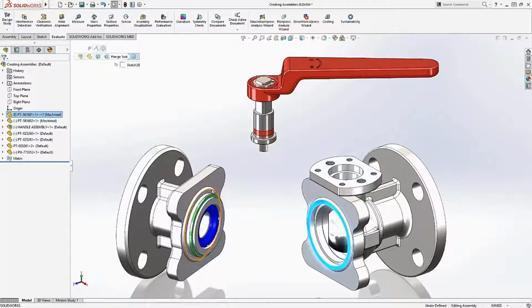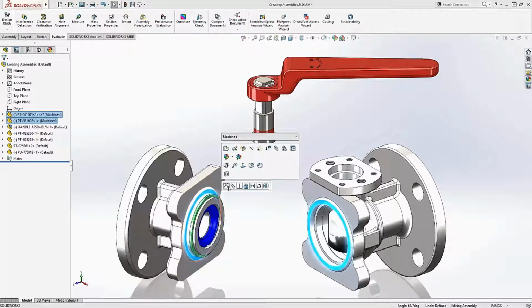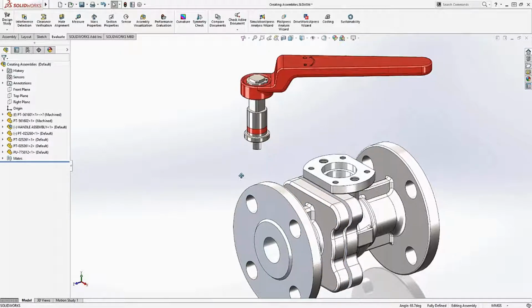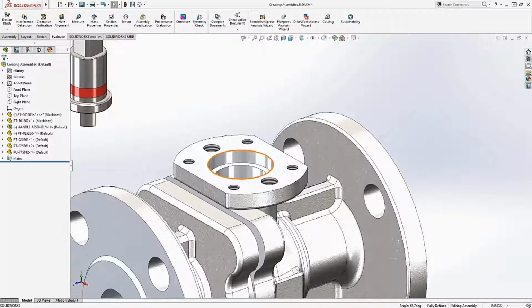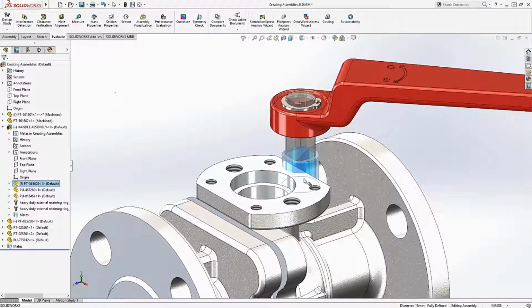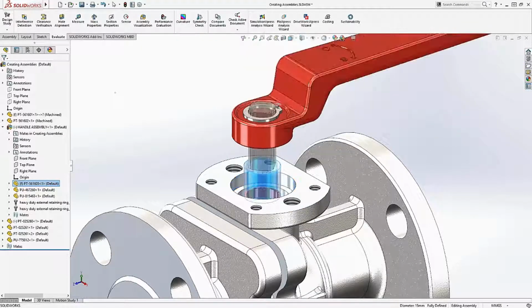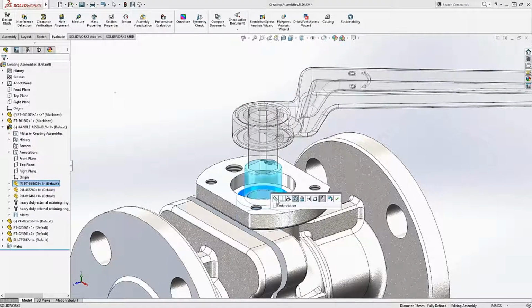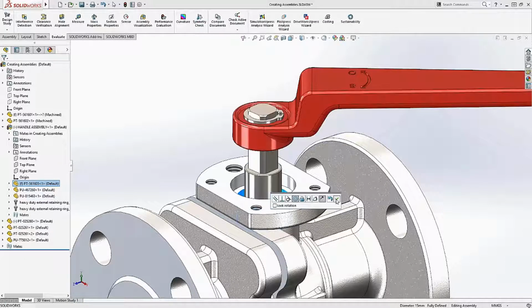When I click two flat and circular faces, I have more choices. I can make them touch one another, or I can take it a step further and not only make them coincident with one another, but also aligned to one another. So here I'll go ahead and press OK. There's also some faster ways of doing this. By holding down my Alt key while dragging the cursor, you'll notice that geometry is intelligent. It understands that it's a cylindrical face. It may want to attach itself to an additional cylindrical face. But you're always given the option to make any changes from the defaults that SOLIDWORKS suggests.